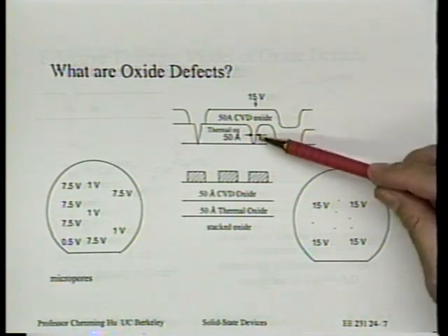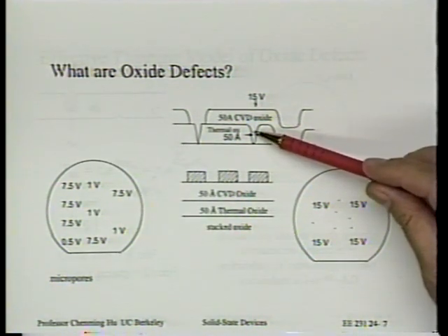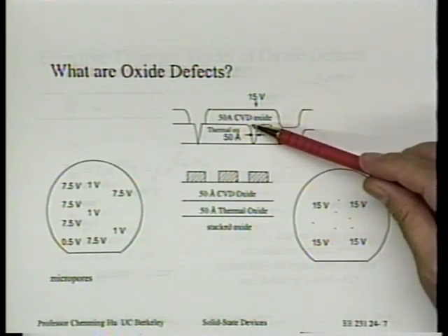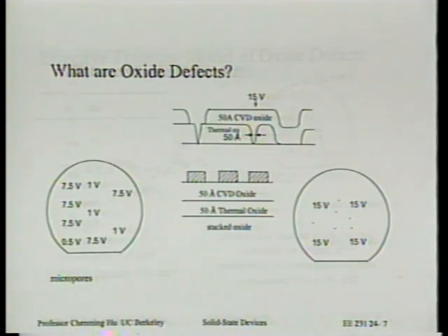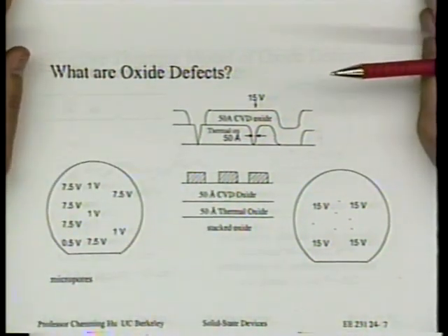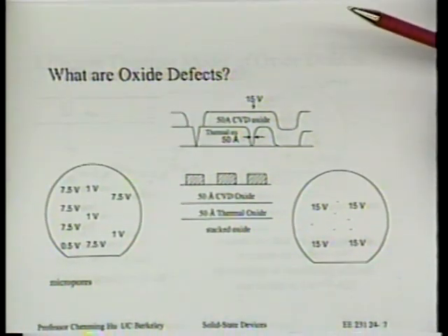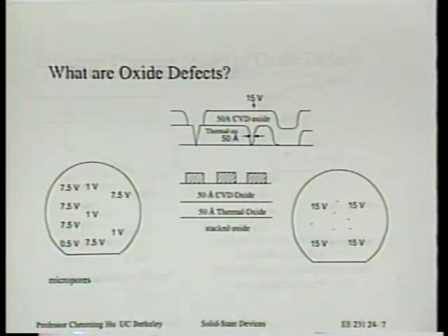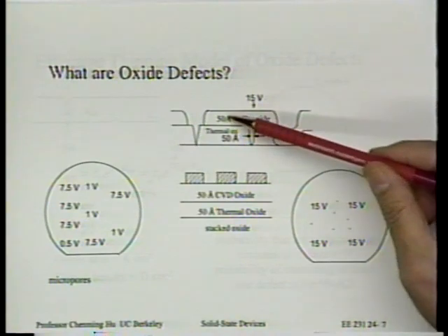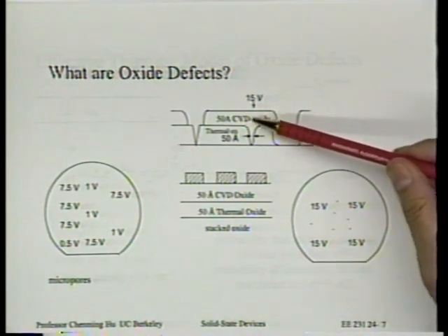So more and more this points to this kind of defect now. What we're talking about as defect may be something very small. Certainly a very thin CVD oxide can fix it, right? And the student Reza Moazan repeated this experiment because we want to see how far we can push this. So he found out actually 15 angstrom CVD oxide, that's the best he could do.